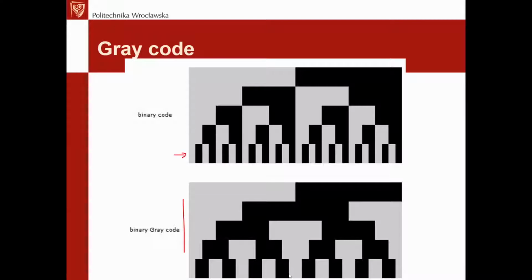The frequency of changes of those positions in the binary code is twice the frequency of changes of the gray code, which means that with a simple change of coding, we are gaining on the possible maximum RPM of this switch or encoder or whatever we have. It's a great gain, mind that.